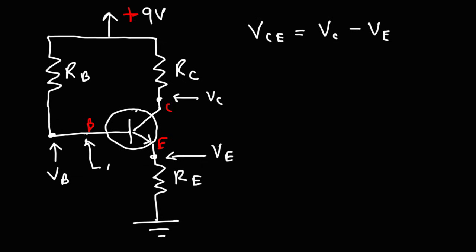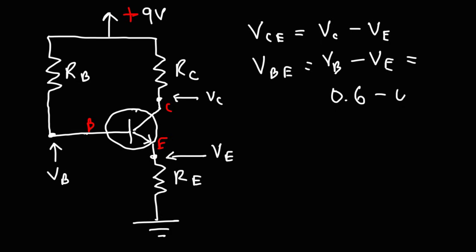Now this here, if you connect the multimeter between those 2 points, that's going to be VBE. So VBE is the difference between the potential at B and the potential at E. Now, for most NPN transistors, this is going to be somewhere between 0.6 and 0.7 volts. So this value is pretty constant. Therefore, you could use it when solving circuits involving transistors.